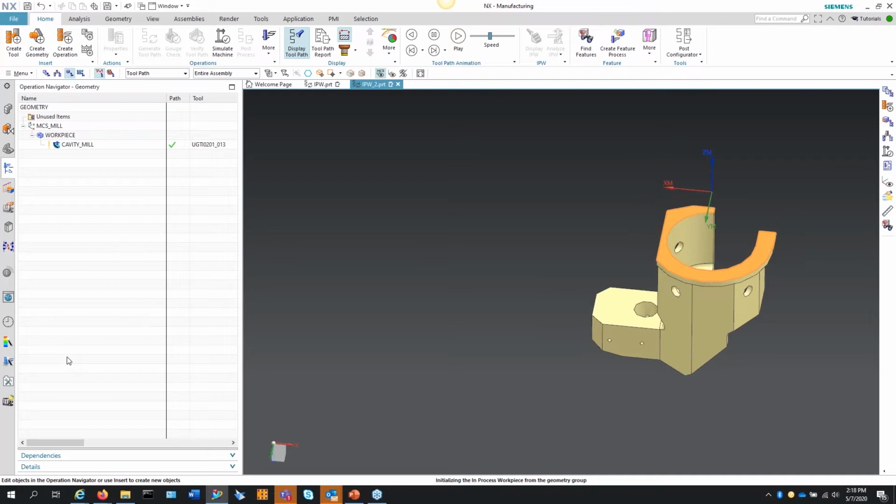If you have 6 sides to a part, you should not have workpiece operations, workpiece operations, workpiece operations. What that does is it confines you into one program. You still get the same associativity factor, but you have to be selective and careful on what you're posting, what you're not posting, with program folders for organization. But when you get downstream 4 or 5 operations, you're going to start losing your connectivity between inside of one file and how it looks at all this data between files. Because NX is very intuitive. It will say, this is my first operation.